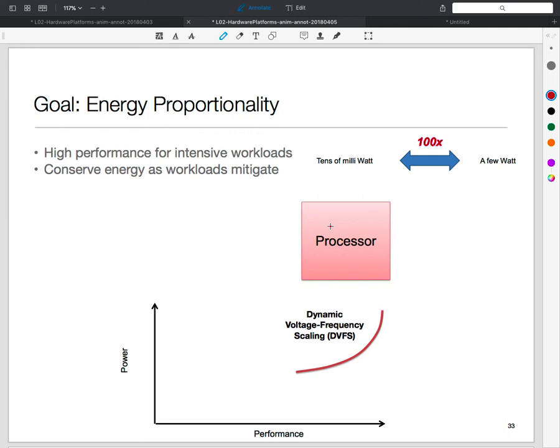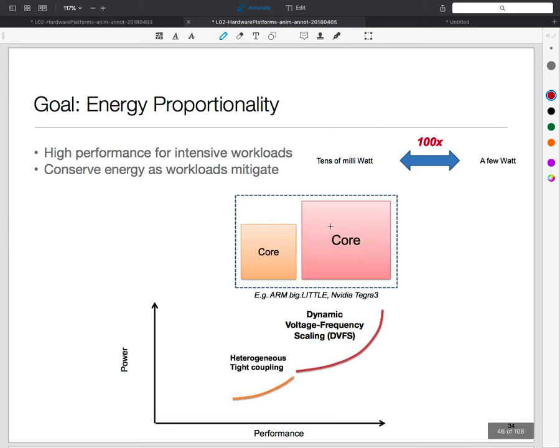What you find are processors where, for example, I can get a big processor and using dynamic voltage frequency scaling, which I talked about earlier, it will span some band. Higher performance comes at a higher cost, until it saturates, and when you go down to zero load but the processor is still powered on, it will still consume some power. So what can I do? Well, one thing I can do is take another processor, which hopefully has a different power-performance profile.